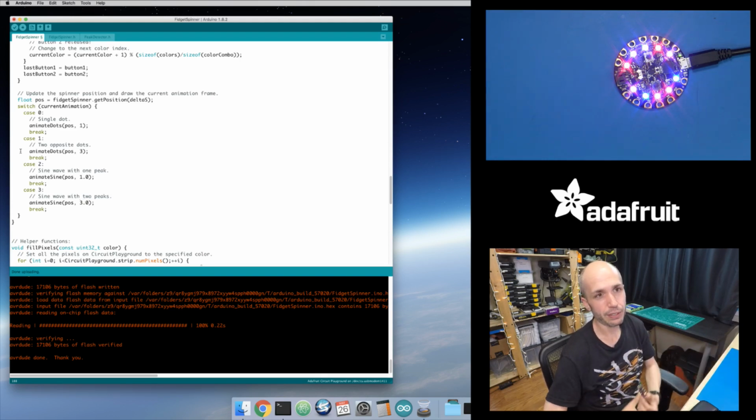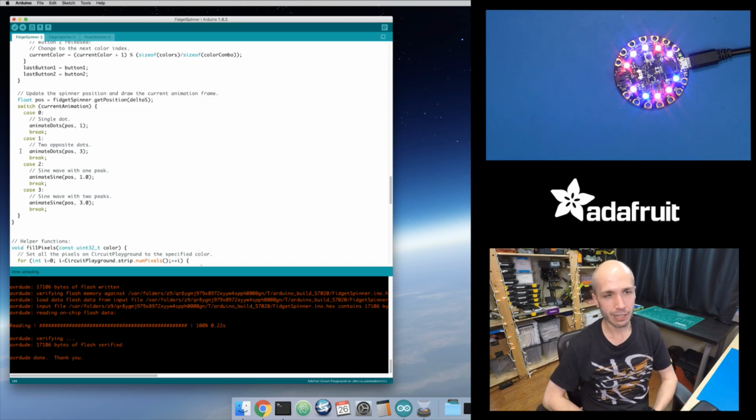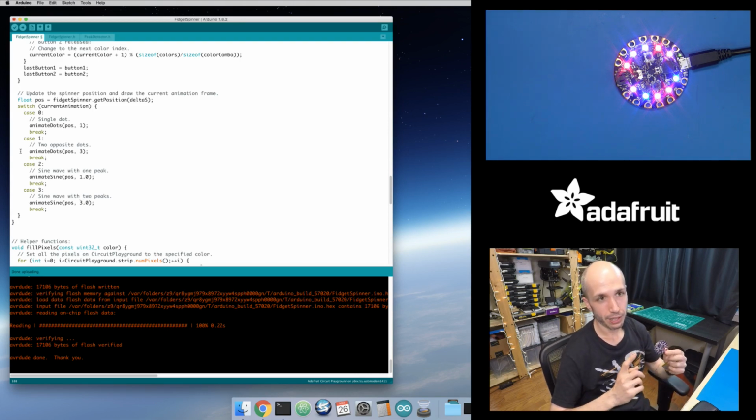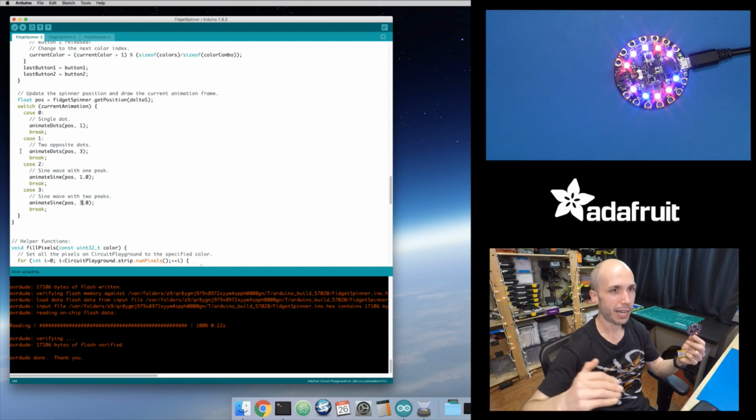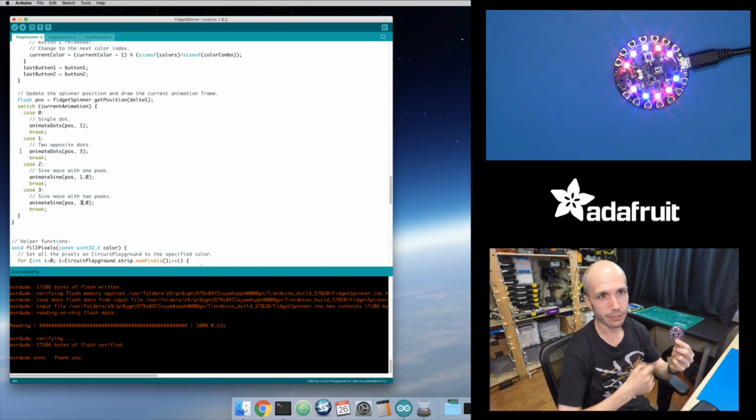And so as we saw in this video, I walked through this peak detection algorithm that uses the average of a window of samples and the standard deviation to figure out, when a new sample comes in, if it's far enough away from that average, based on some number of standard deviations, we've detected a peak. And so then we can start spinning the fidget spinner around like that.